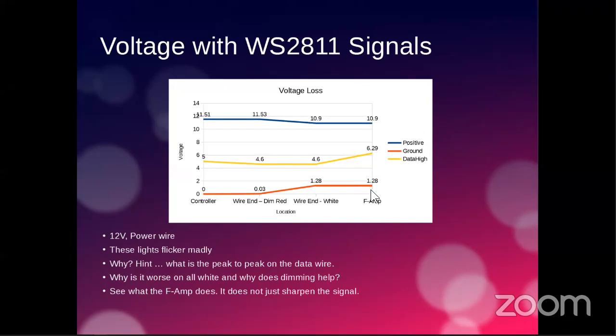This would then also be 0.65. And this would be 0.65 plus 5. So it would be 5.65. It wouldn't boost it to 6.29. It's really only boosting it relative to the ground by 5 volts. So whatever that was at that point, it's going to do it. So if this was 2 volts here, this would boost it to 7. Assuming that this voltage is higher. Now, this would be very different if this was a 5-volt pixel. Very different.